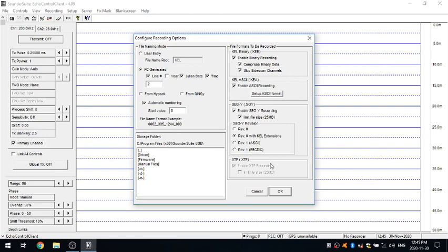As mentioned briefly earlier, if you have your Knudsen system set up with side scan channels, then this would be highlighted here and you'd have the ability to record XTF, which is an extended Triton format, which again is an industry standard for side scan, so it'll be able to play back with some of your viewing software. So just again quickly, under the recording options, different options for naming, where you're going to record the data, and the different formats that you're going to record them in.